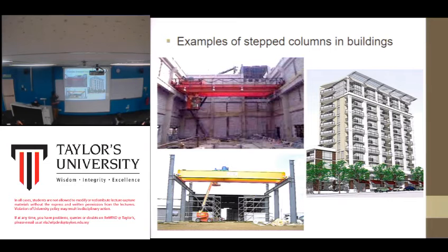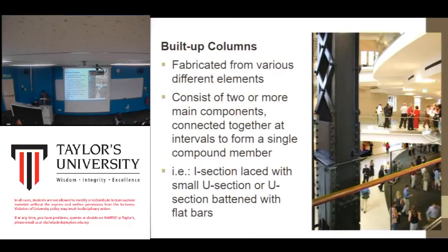Okay, so as you can see from here, it's the same. So you have bigger column, but in this building, basically the function of the step column is more or less like this. There's something here, right? So there's a crane or something. So that's why you use step column basically to allow for this structure to sit on the beam or something like that. Right?